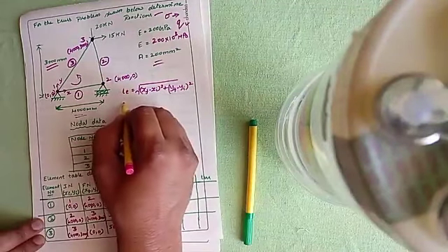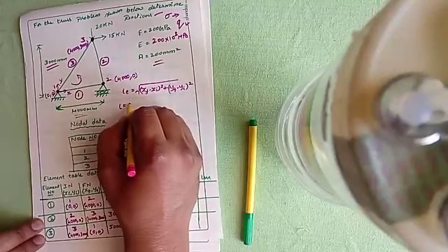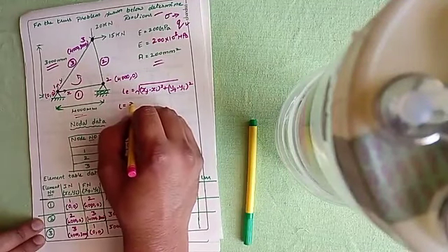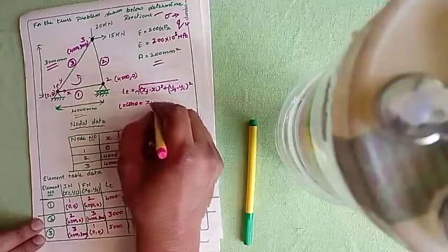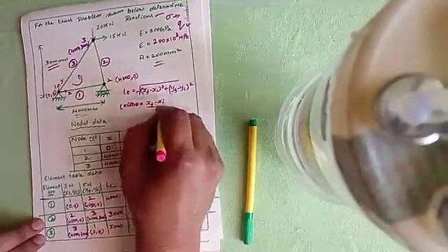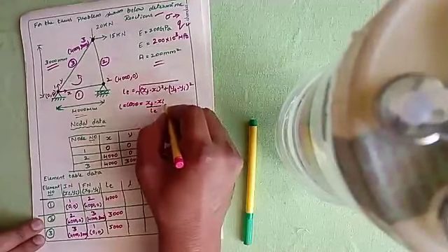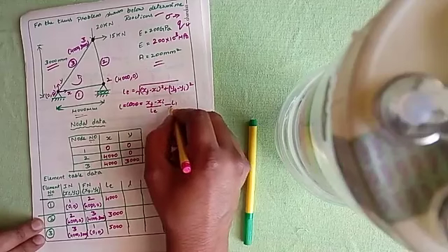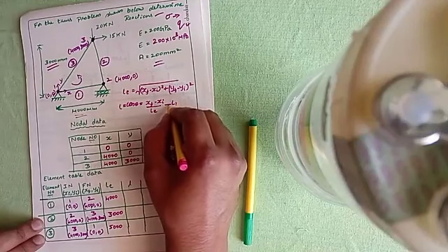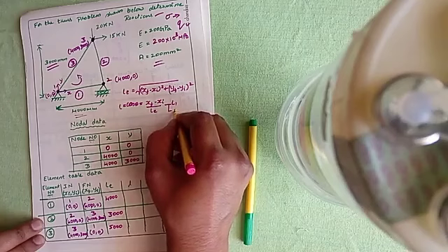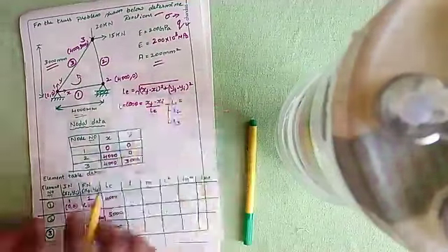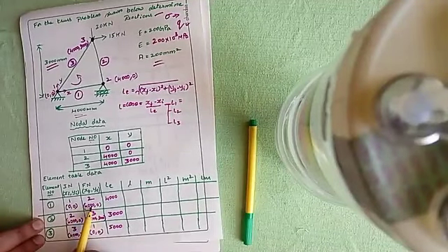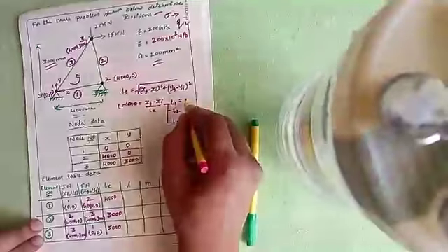And what is a direction cosine L? L is equal to cos theta, which is equal to xf minus xi divided by the length of the element. If you try to calculate L1, where 1 indicates element 1, and L2 is for element 2, and L3 is for your element 3. So xf, now come to element 1. Xf is how much? 4000. Xi is how much? 0. 4000 minus 0 divided by 4000, you're going to get 1.